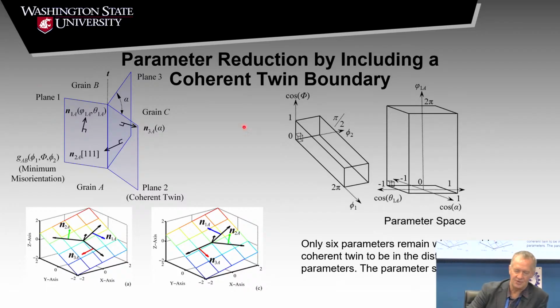Okay, so this is reducing the space, and there's a lot of assumptions you can put in saying, okay, well, if I have a triple line, then the dihedral angle is not going to be 360 degrees, right? It's going to be some fraction. So he didn't allow the dihedral angle to be more than 180 degrees. That was something he said, I'm just going to ignore that part of the space. And that allowed him to calculate things easier just by cutting down the space. So he made these types of assumptions.